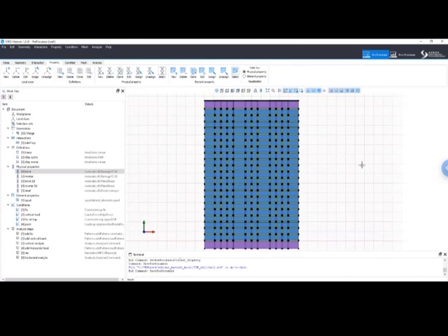Here I will show you how you can do it quite easily with a user interface and with a constitutive model that we have implemented in our own version of OpenSees. So if you downloaded STKO plus OpenSees, the OpenSees version that you have there has an additional constitutive model for concrete and masonry that is quite effective and quite robust because it uses a particular integration algorithm that basically makes the model almost always converge.